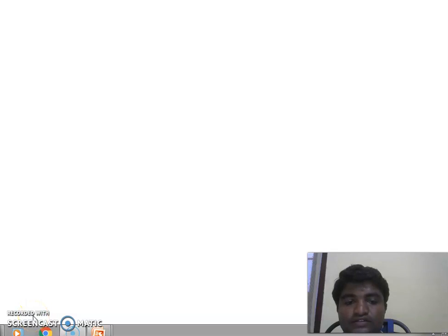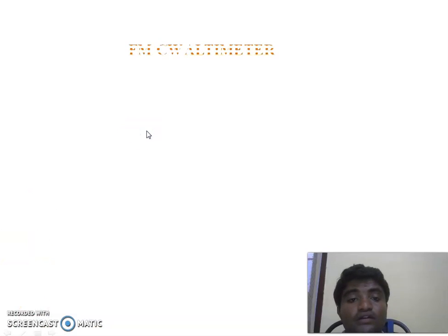In today's class, I am going to explain one of the applications of the FMCW radar. The FMCW radar can be used as a radio altimeter. The application is the FMCW altimeter. It is used in aircraft to measure the height between the surface of the earth and the aircraft.